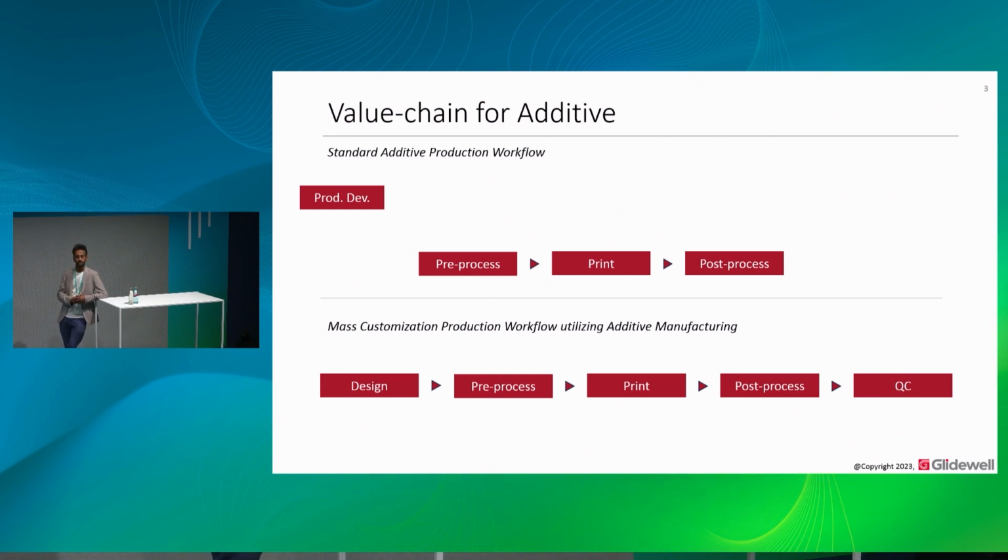Some of it has to do with nesting and optimizing, making sure you can fit as many bike grips within your machine, making sure that the support structures are out of the question here because it's SLS. But yeah, so just identifying certain specific features that are easier to achieve because you're using, let's say, a TPU material, right? Like using an elastomer